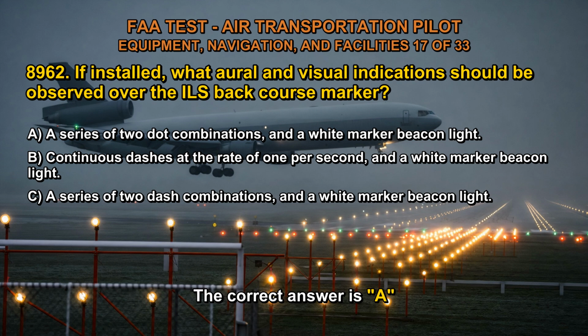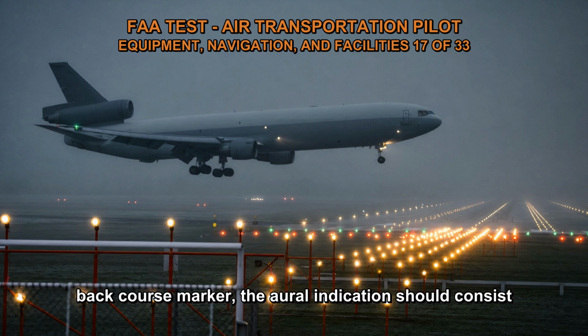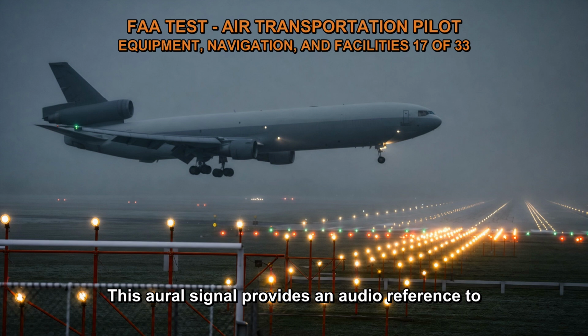The correct answer is A. If installed over an instrument landing system, ILS, back course marker, the oral indication should consist of a series of 2 dot combinations. This oral signal provides an audio reference to the pilot that they have crossed the back course marker.